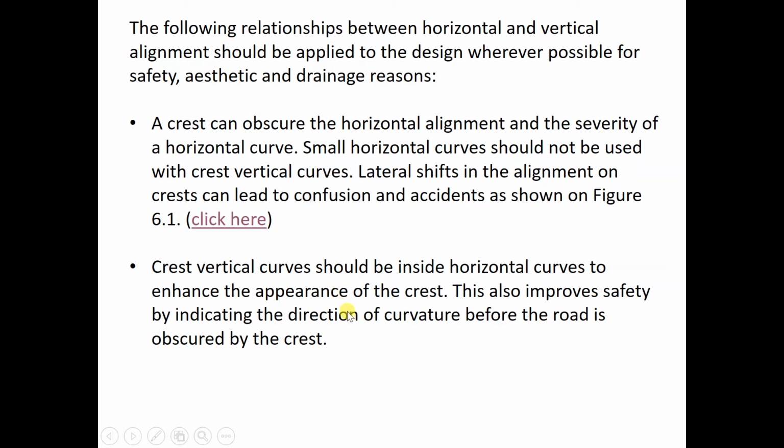Okay, crest vertical curve should be inside the horizontal curve. Crest vertical curve should be inside the horizontal curve. So the vertical curve should be inside the horizontal curve for safety reasons. Okay, this also improves the safety by indicating the direction of the curvature before the road is obscured by the crest.